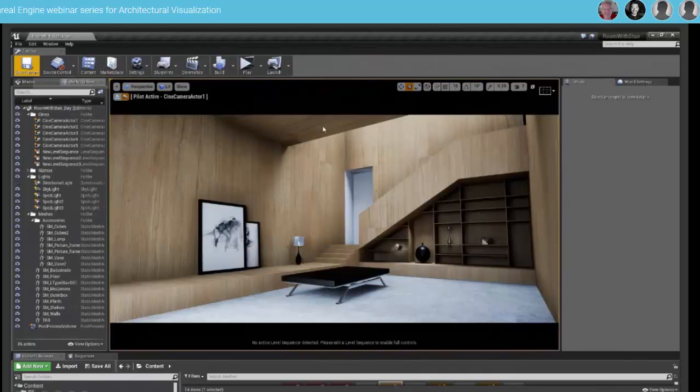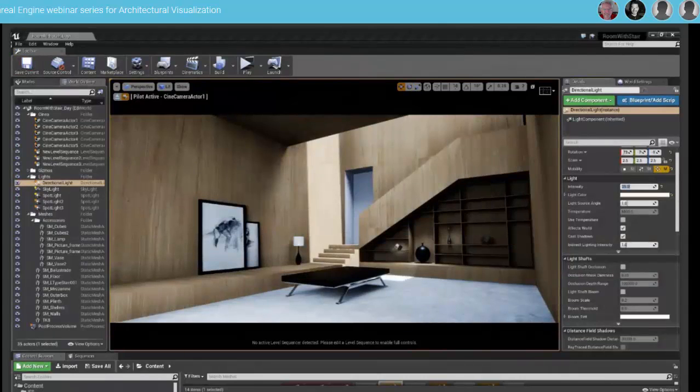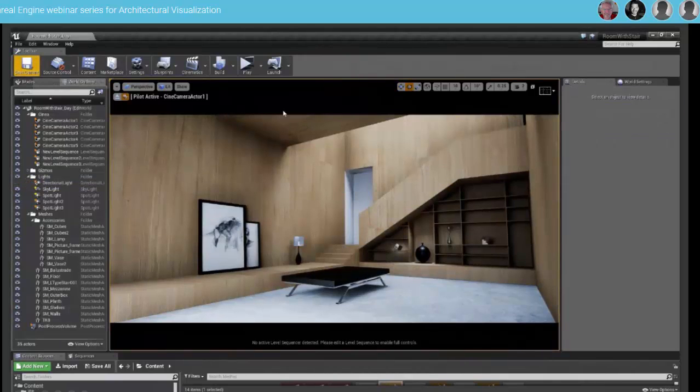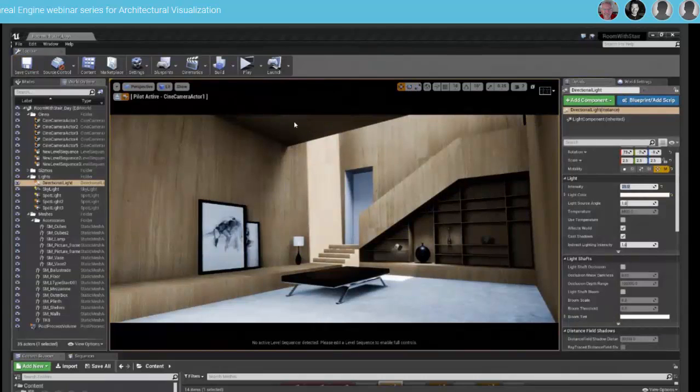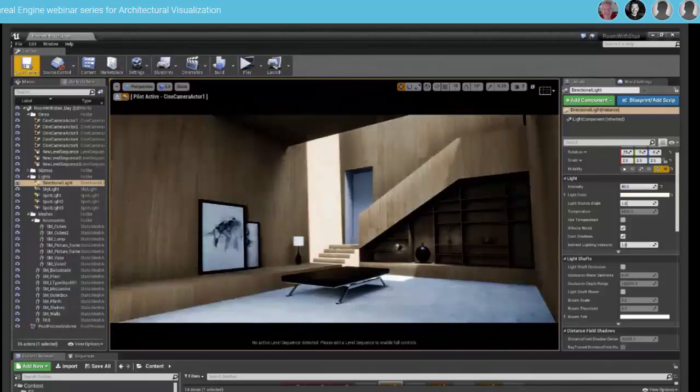effect where the tone mapper of Unreal is going to start working for us. If you observe, the ceiling is fairly well exposed, and when I bring in a harsh sunlight, this becomes quite dark. It's because the tone mapper of Unreal is compensating for this strong sunlight coming in. So if I make it even brighter, we begin to really work with changing the mood of the scene.